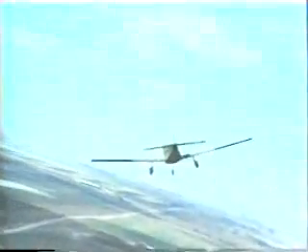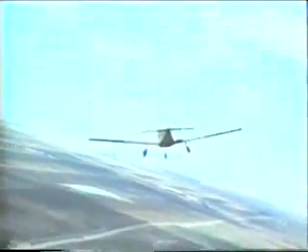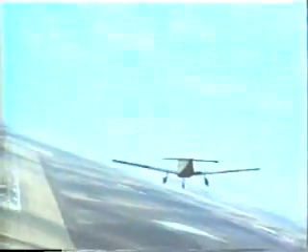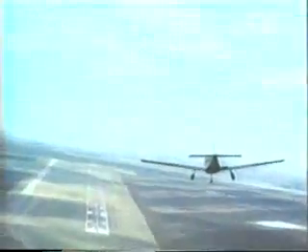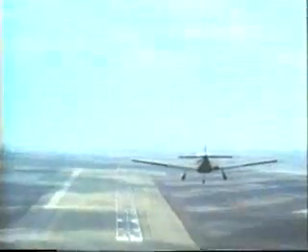These statistics help you see the need for avoiding steep turns at low airspeeds, a flight condition common in stall spin accidents. This typically occurs when pilots overshoot the turn from base to final, then tighten the turn to align the airplane with the runway.